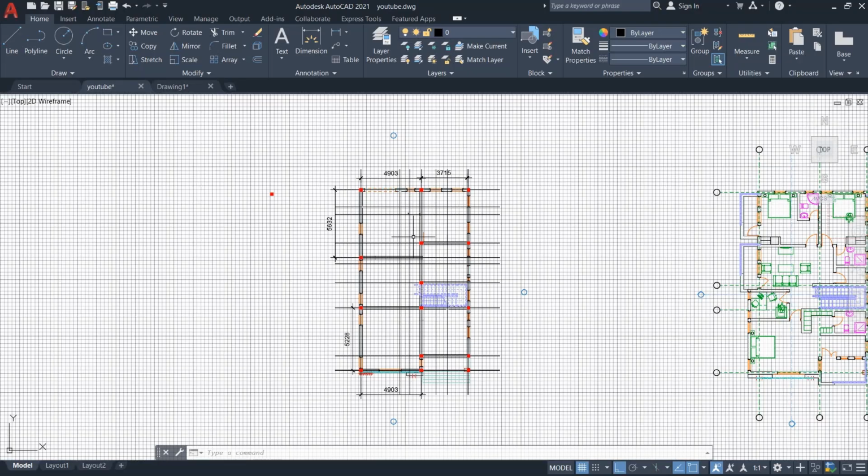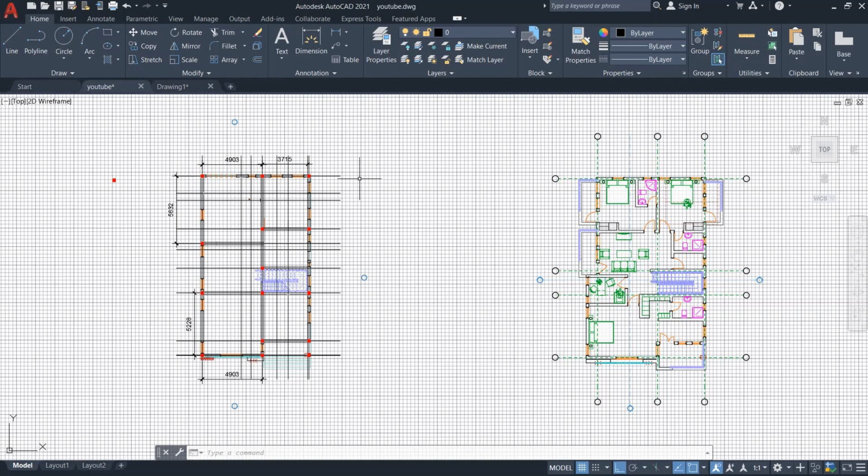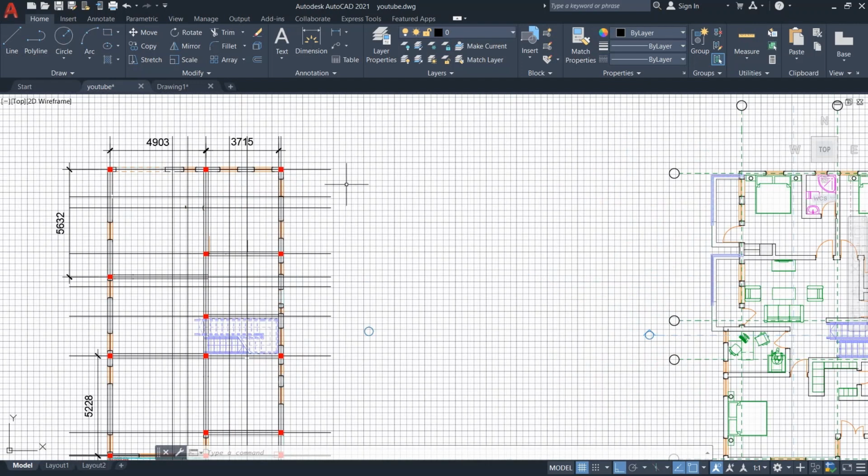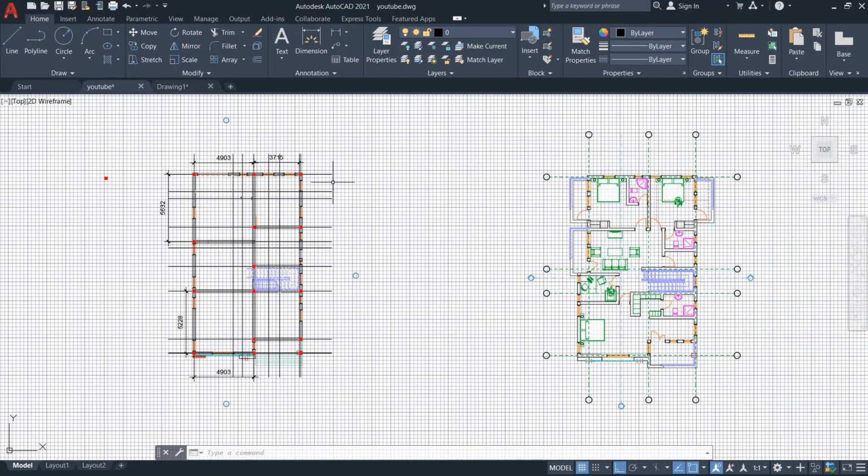Okay, so as you can see now, we have formed the general arrangement for this. This is the general arrangement for the first floor. This is what is going to be carrying the first floor. Now what we have to do is to superimpose the grid and column placement from the general arrangement done on the ground floor onto the architectural plan done on the first floor. This would help us to know if there's any column that is coming out of the wall that is in a pathway or blocking, whether we can stop it and initiate a floating column to continue.